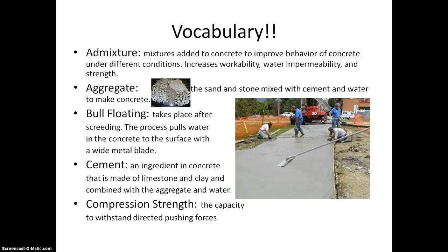Bull floating, it takes place during installation, and it's after the screeding of the concrete. We'll get into this more when we talk about installation. But this is the process that pulls water and the concrete to the surface, and it really levels off the surface and packs down the aggregate.